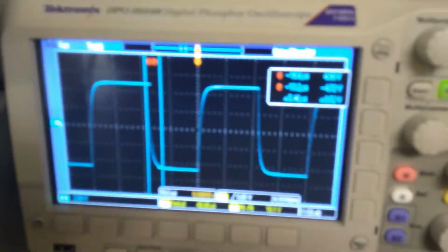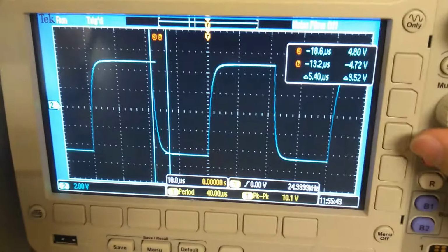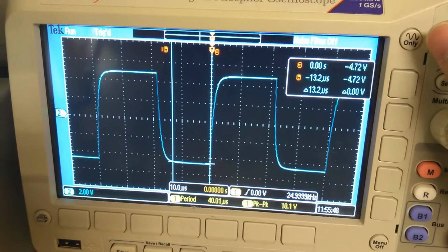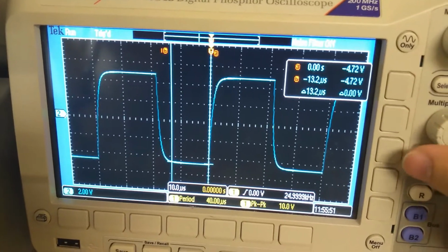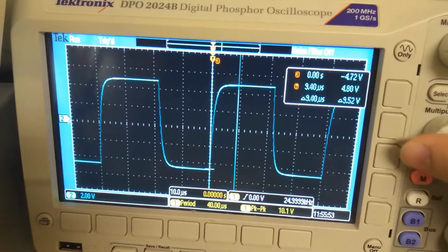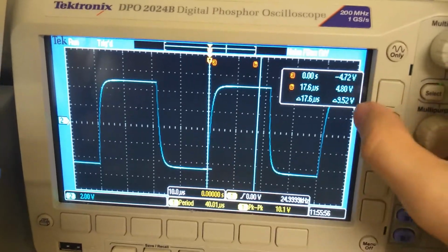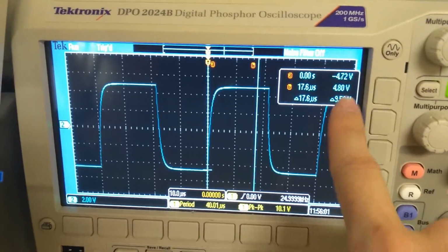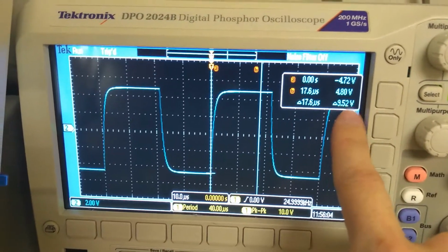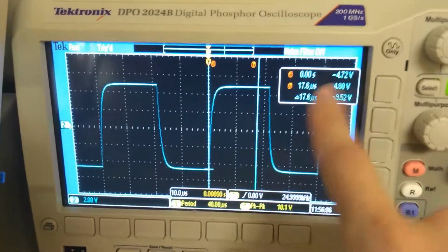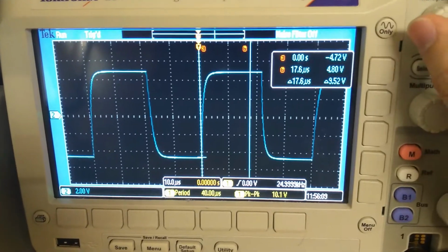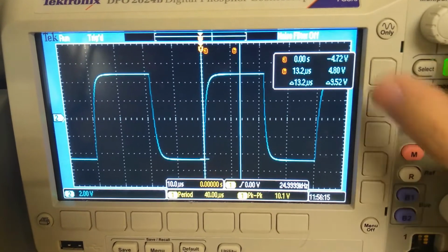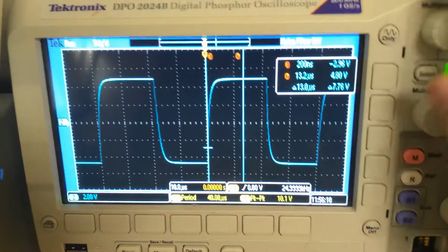And now we are measuring the charging process. Again, we put the first cursor at the starting point of the charging process, and the second point at the end. Okay, so when it's fully charged, it's about 9.6 or 9.52. It charged to about this voltage. So we move the second cursor to the left until this number starts decreasing.